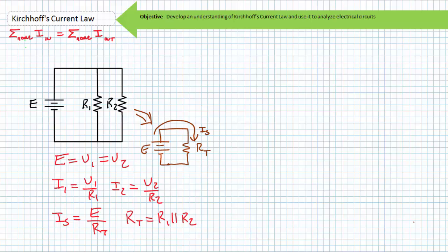Regardless, if one was to idealize this two resistor parallel combination as a single resistance RT, it is readily apparent that the current through it is obviously equal in magnitude to the source current IS. It stands to conjecture that R1 and R2, those resistors that compose RT, draw representative portions of this source current, no more, no less. It can be said, therefore, that IS equals I1 plus I2. We can go any number of rounds with Ohm's law and perform any derivation you wish, but the easiest method I've found to convey this simple fact is this.